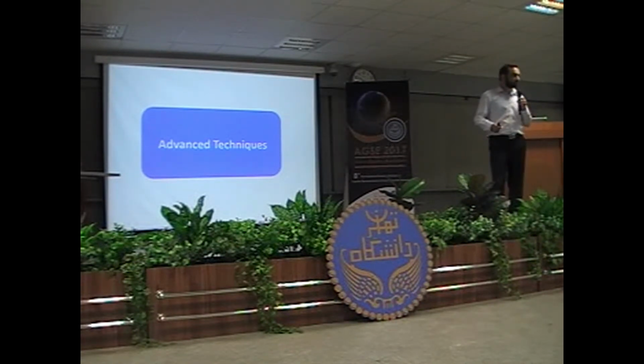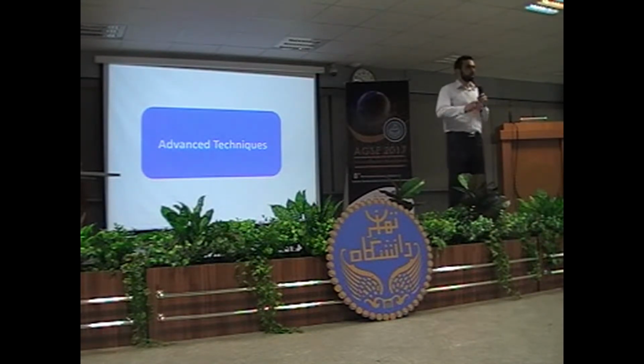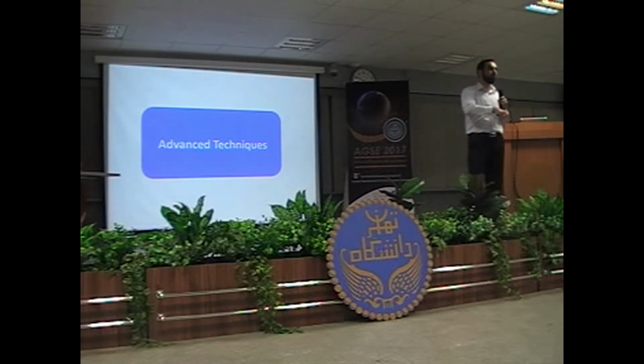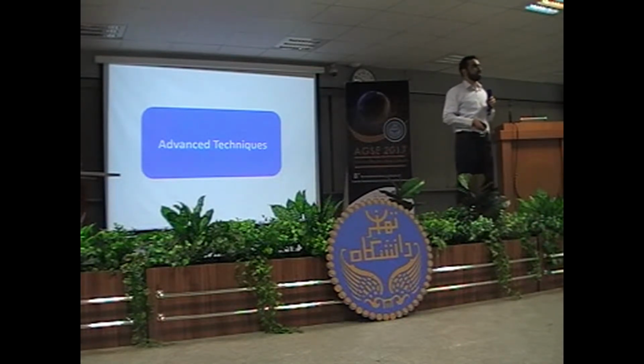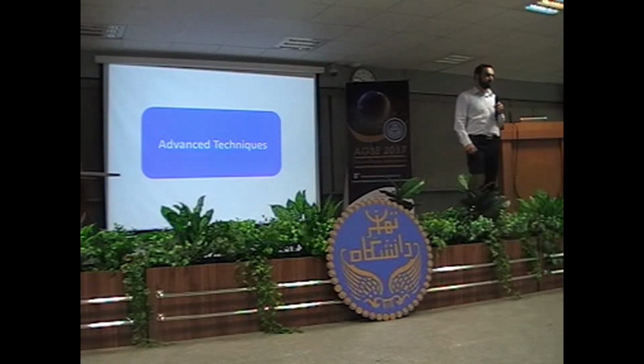Maybe if the penetration is very important, because in some applications of geology on the ground there are soil, so the rocks are beneath the ground. If the penetration is important, you should go for the longer wavelengths. Yeah, P band or L band. So if you have an outcrop of the geological rocks, then the X band or C band will be good. But if the penetration is important, you should go for the longer wavelengths. But see, the P band is not applicable in the space-borne. We don't have any P band space-borne yet. So P band is just airborne. But L band we have.